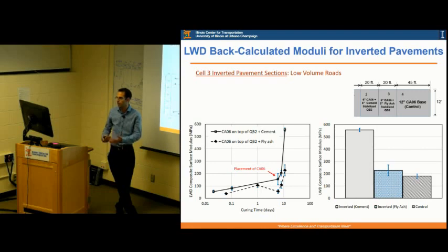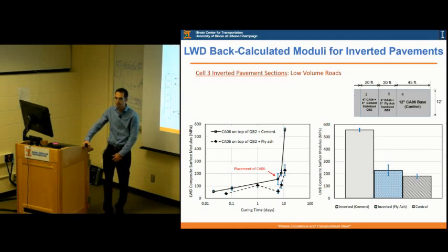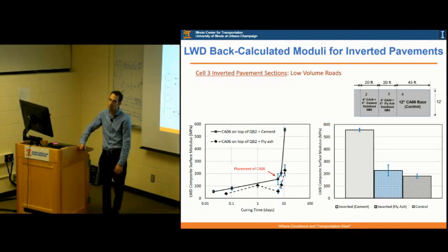Cycle after cycle, you see a big drop in the strength and performance of those stabilized layers. With the unstabilized ones, I don't think the effect will be very high, especially for the open graded ones, like the large blocks with the QB. I don't think they are highly moisture susceptible, since you don't get capillary action of water coming into those layers easily. So I don't think they will be highly affected by freeze-thaw compared to the stabilized layers. It's like you lose 10 psi with every cycle or so. The stabilized material loses strength over time with the freeze-thaw cycles. Yes.